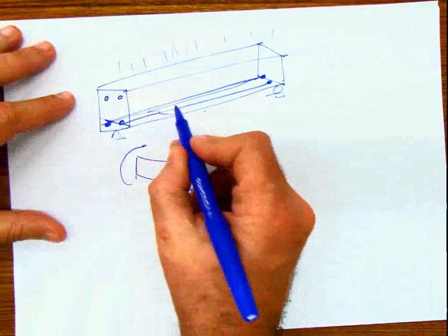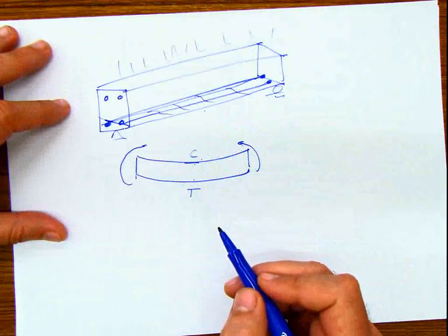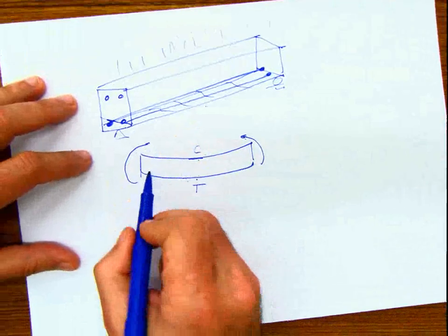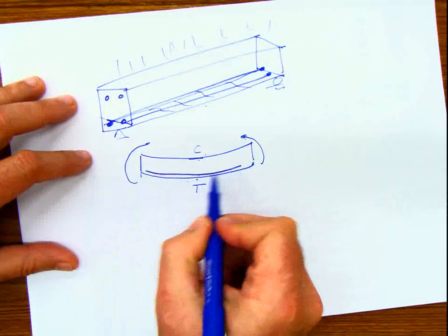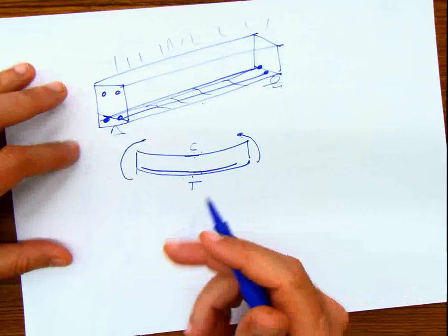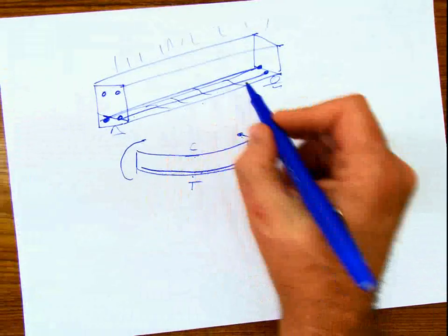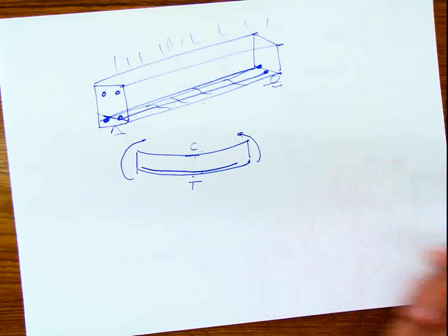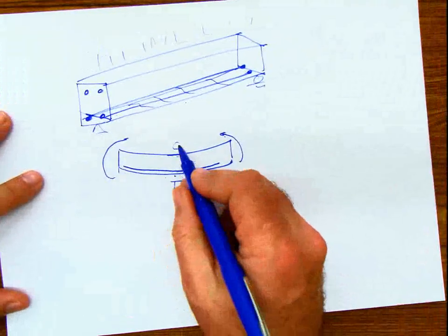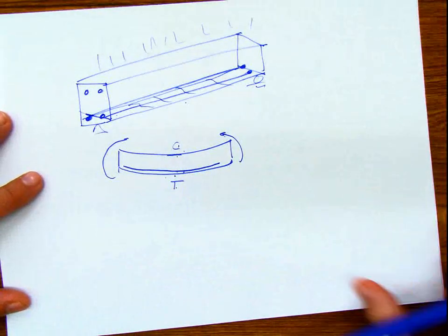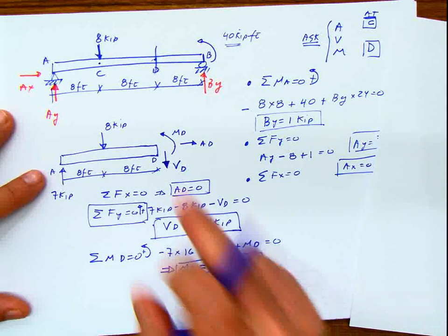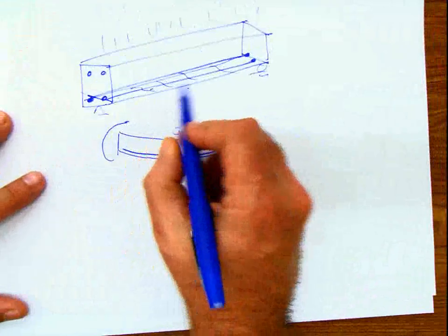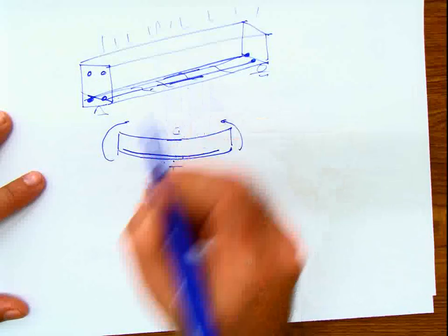So this part is going to crack in the structure, and the structure can collapse. That's why you supply this area of tension with steel rebars to absorb that. And this longitudinal steel is calculated with the moment that we have in that diagram. A positive moment indicates compression on top, tension on the bottom. The moment that we just calculated here is a positive moment at that point. That means that if this is a reinforced concrete beam, I'm going to have rebars placed on the bottom part.